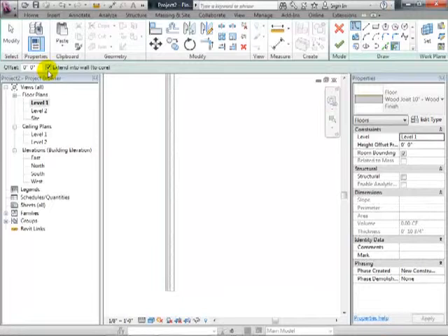But the most common condition we typically see is that you bring the floor joist right up to the face of the studs, or to the edge of the interior, like concrete blocks, whatever it is. So extending into the core just says let's match the core boundary, that structural layer, as opposed to the outer surface, so the floor is not bleeding through. Okay. But if you bleed through, how do you?